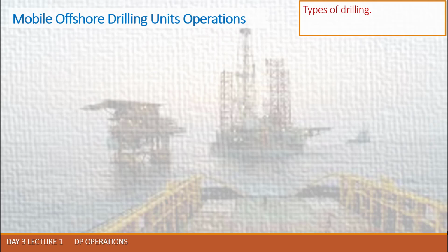Because the DP system always receives the information about the riser angle, and specific software applications for riser angle monitoring are available for the drilling industry, which may also be a part of the DP system. The DP system may automatically apply large amounts of thrust compensation for what it perceives as a large positional offset. This erroneous thrust input just compounds the existing problem with the riser support system.